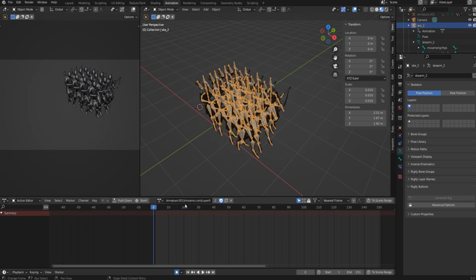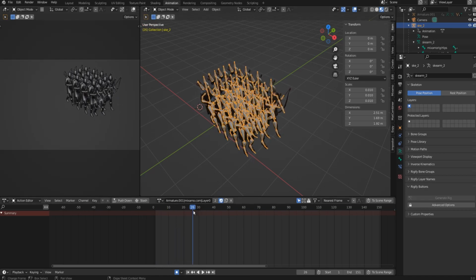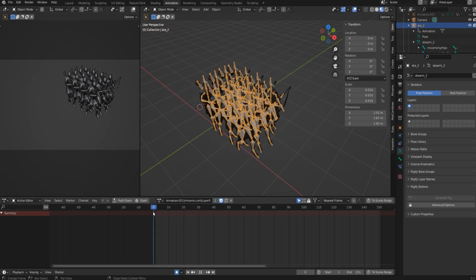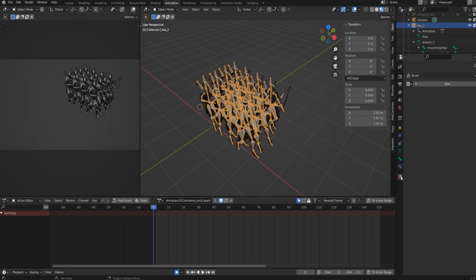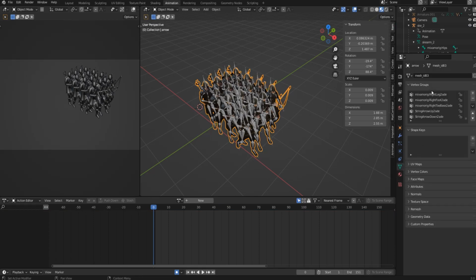You may want to check my previous tutorial on how to merge skeletons in Unreal and keep the animations, link in the description. Before exporting, make sure everything is working properly. That there are no bones with the same name and that you have only one material and one texture that is being used by all the units. Note, if all the units use the same material, you can simply delete the copies. All units will default to using the same material.